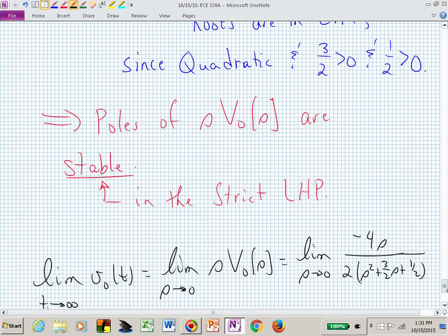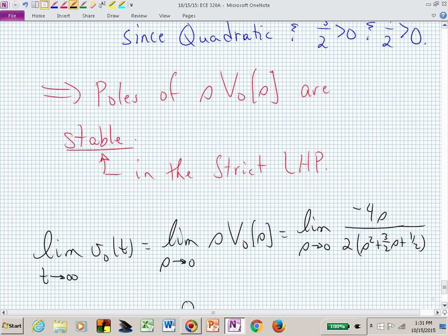So why did I factor out the 2? My technique for finding whether those poles or those roots are in the left half plane is based on a polynomial being monic. Then I just have to focus on the s to the 1 coefficient and the s to the 0 coefficient, those 2 coefficients. Meaning the leading coefficient could have been a minus 2. I would need to factor that out and then worry about the coefficients that remain.